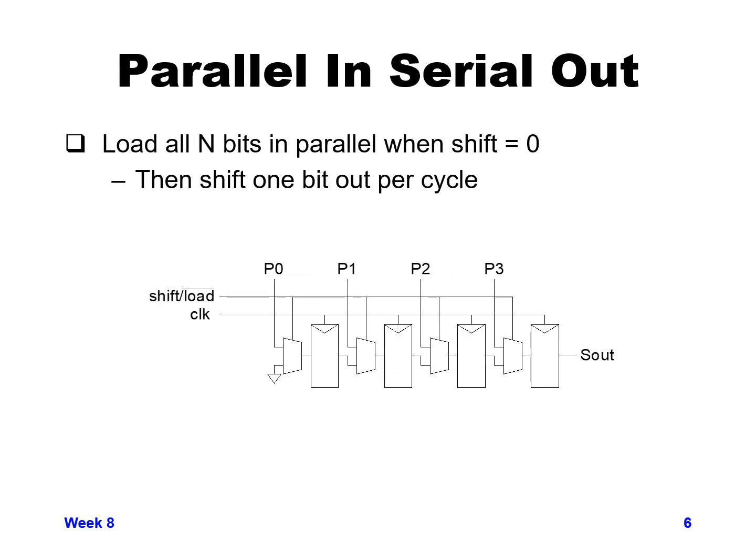So the previous foil went through serial in, parallel out, or SIPO. This foil is the flip of that, where we have parallel data coming in and we're reading it serial going out. Like in the last foil, we had 4 bits. So here we're loading all 4 bits at the same time into the 4 registers, and then we're shifting out 1 per cycle.